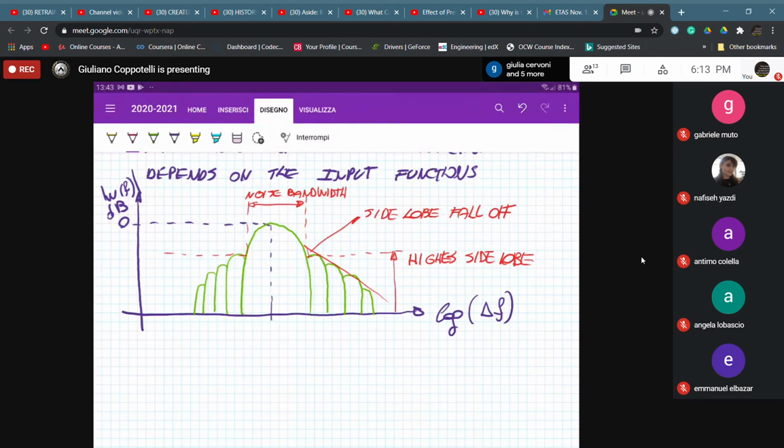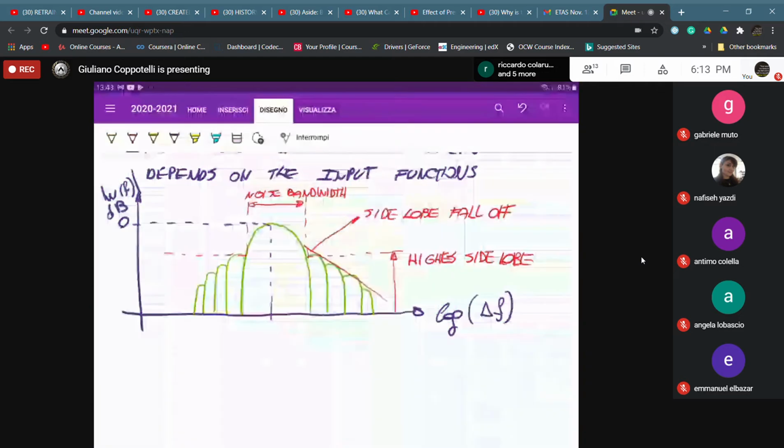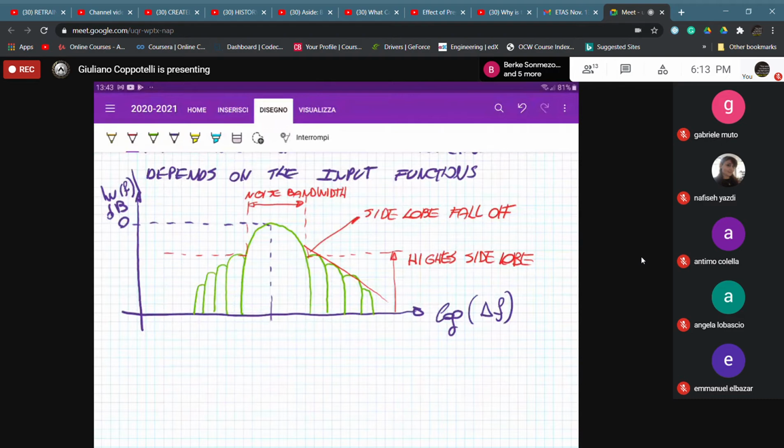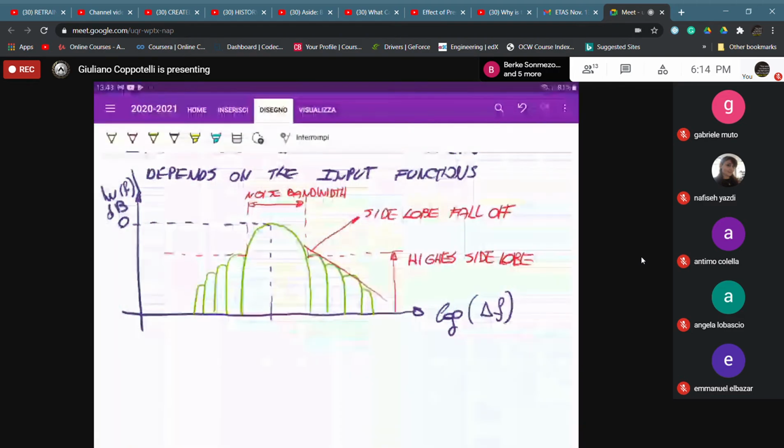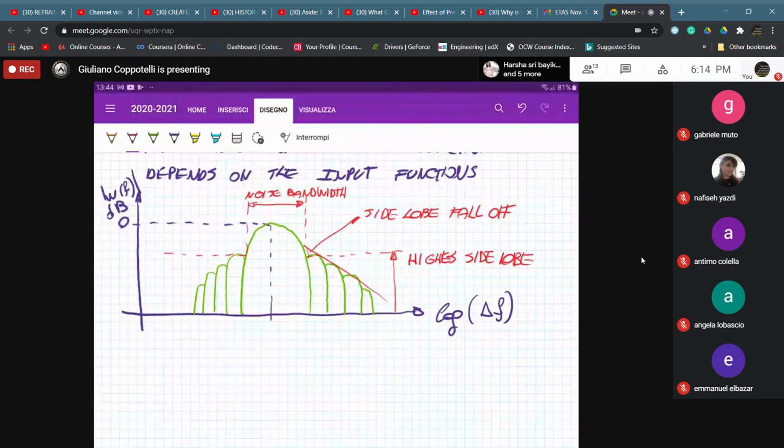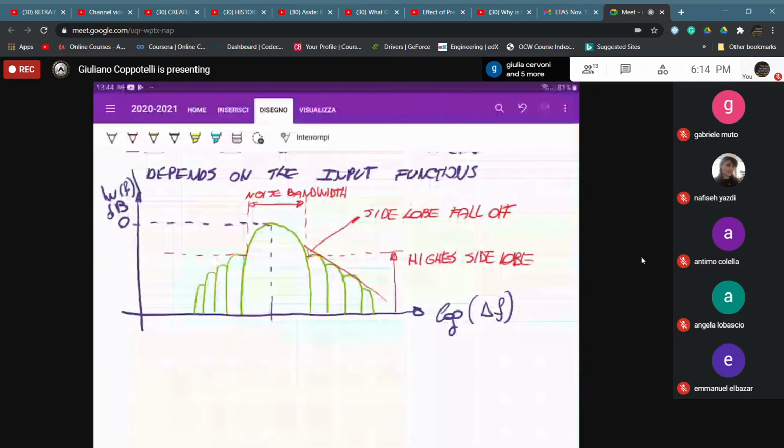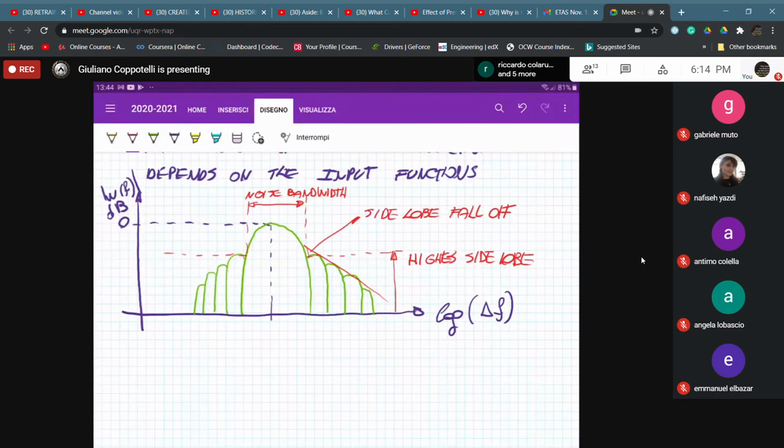Therefore this windowing function varies the amount of energy that is squeezed into the central lobe as compared to the side lobes. All the energy across the center frequency is passed to your analysis. What is outside the center lobe is practically reduced; there is a lot of attenuation, as we can see from this picture.